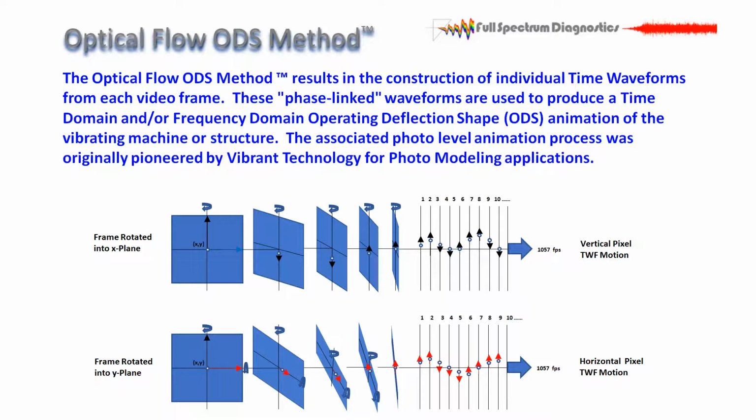It's a time waveform. So in that time waveform is the entire frequency range. I have phase for everything. I can do what's called an operating deflection shape from the time waveforms. And that's the base units that we'd be starting with.